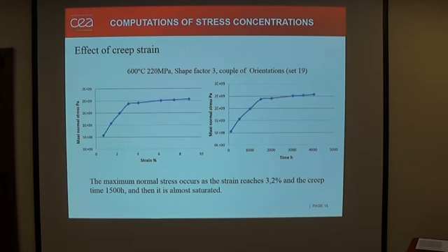We then studied the effect of creep strain, and we found that the maximum normal stress occurs when the strain reaches 3.2% deformation, at a creep time of 1,500 hours. That's why, for the following, we do a calculation up to 4% deformation and 2,000 hours.